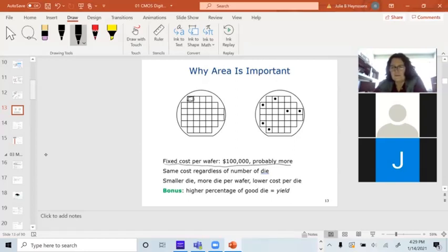Now, another thing that's going on is that when I test the wafer, one of the first things I do is I put a probe card down on here, and I actually make contact with these really sharp needles with the die, and I put power and ground to every single chip. The ones that I measure no current from, they actually physically put big black dots on them. And that's telling me that those are bad, and don't even package them. Don't spend any more money on them. They're already dead.